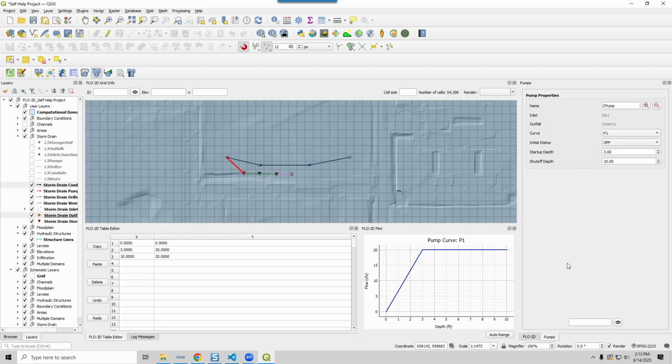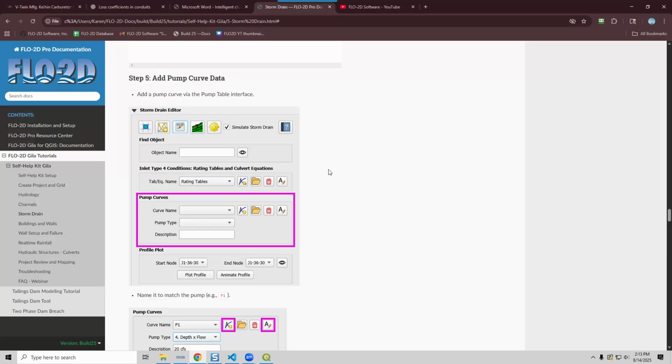And if you need any help on any of these, you can go to OpenSWMM. They have a lot of good examples of pumps. And then you can ask ChatGPT to build you an example of a SWMM pump for a specific configuration. It'll help you figure out the right data to put in for your pump. It'll also help you figure out rules and different things like that. Okay, what's next? I guess we just go back to the manual because I forgot what was next.